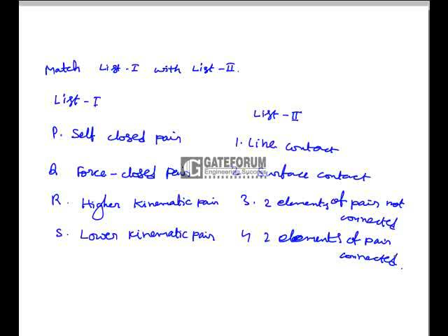Here if you consider self-closed pair, in this pair two elements of pair are not connected, and if you consider force closed pair, two elements of pair are connected, so that here P is matching with 3 and Q matches with 4. And here higher kinematic pair is nothing but line contact, and lower kinematic pair has surface contact. So that R1 and S2 in the option, the right option is C.